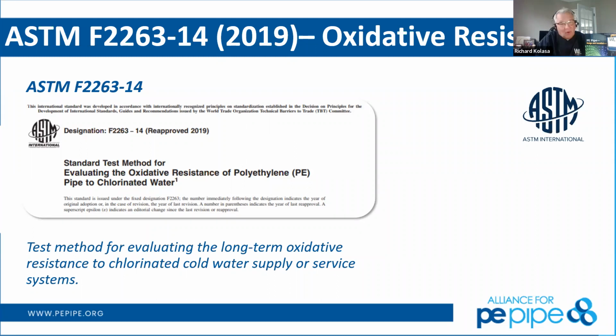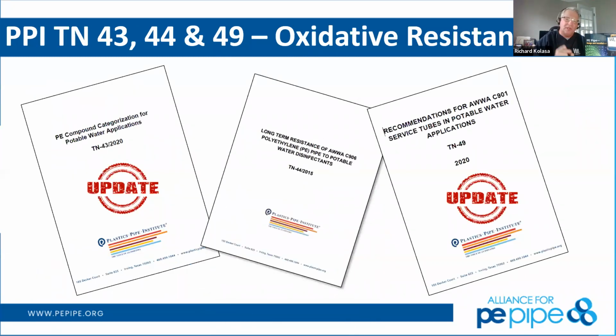And so with the amazing science and engineering done through this understanding of how it can negatively affect performance, the resin suppliers went out and developed products that would resist that as well. They've really changed and improved the product, which puts us in our fourth generation, which is referred to as ASTM D3350 PE4710s. I think that's probably enough. I encourage everybody to look at this. It's one of the most popular questions that I receive on a regular basis: what is the oxidative resistance of polyethylene?